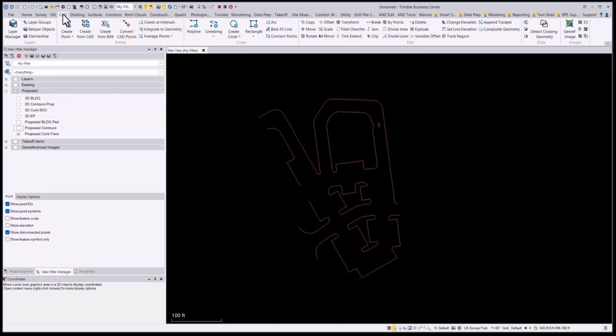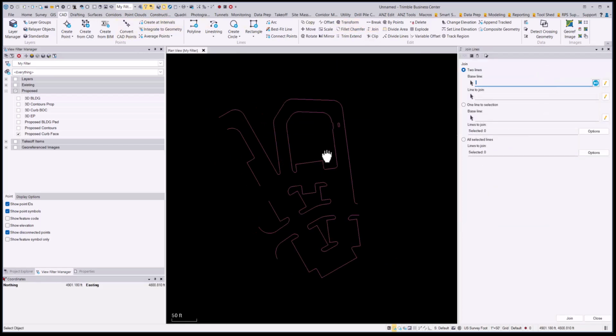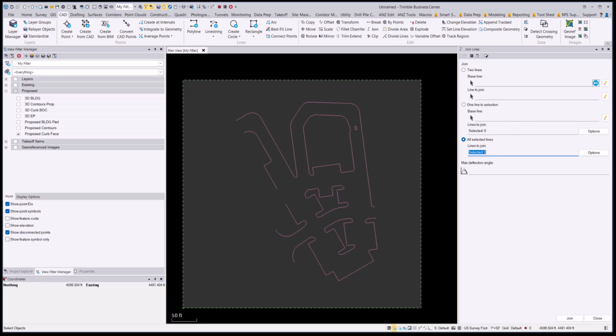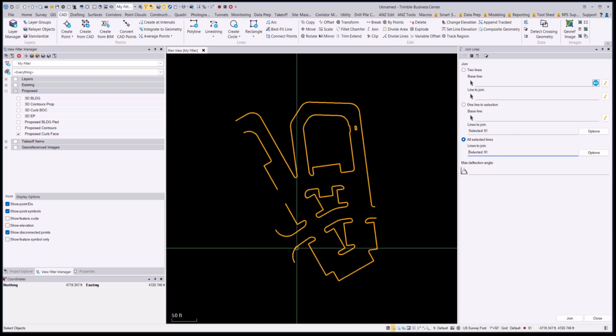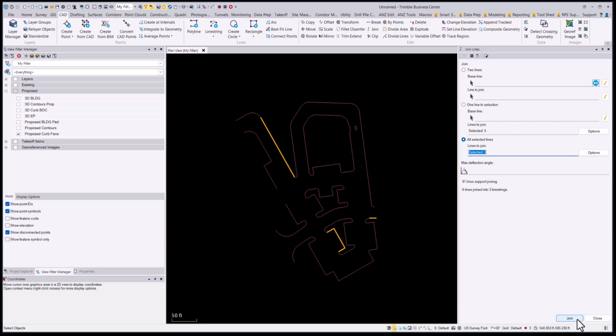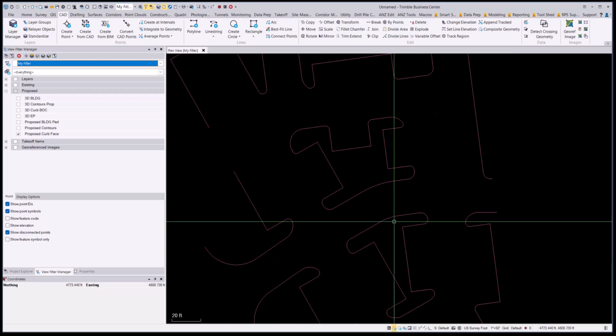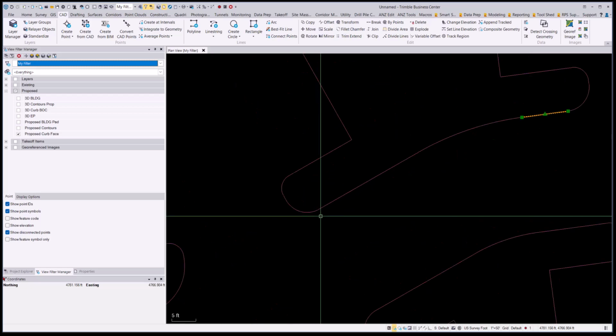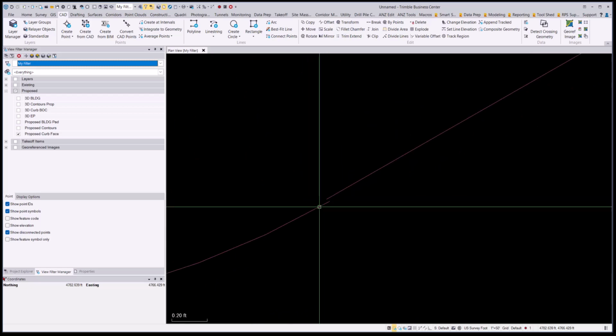Let's go to the CAD and let's go join and let's do all selected lines, and I'm going to do a crossing window, so I'm going to select it all and say join. So 91 lines support joining, 6 lines joined into 3 line strings. So it did do a little joining. So let's close, but we still have a lot that it didn't do. All right, and I knew it wouldn't because you can see these items are not exactly endpoint.